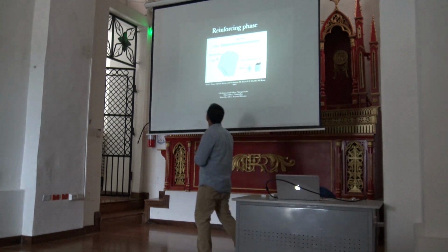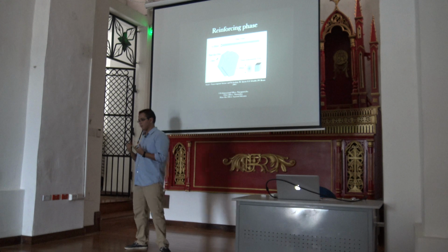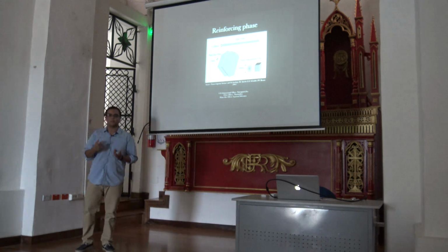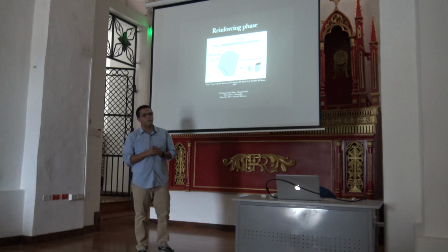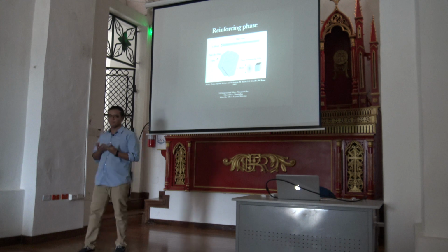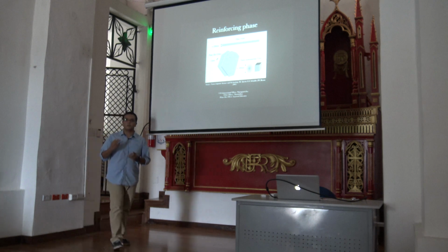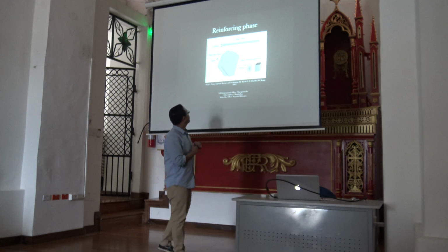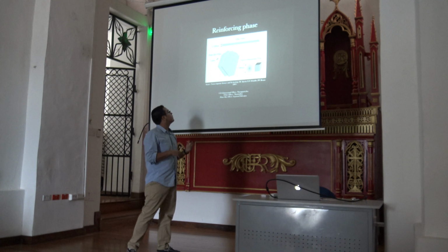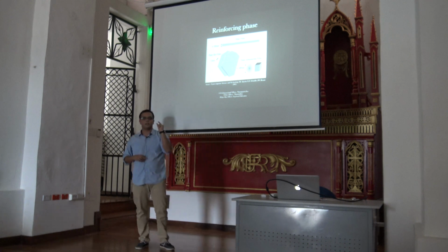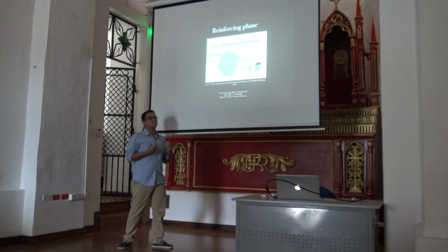So I'm going to talk about these reinforcing phases, which are the nanofillers. Here we can see the first one that I told you, a nanofiber. Its diameter is less than 100 nanometers. The most common types are the carbon nanotubes. The second one are the particle fillers that are three-dimensional particles, with a size of less than 100 nanometers in their larger dimensions. And the third one are these big ones from here, the plate-like fillers. The most common of these are the layered silicates. What's special about these is that the most typical thickness is only 1 nanometer, but the aspect ratio is about 25 or above.